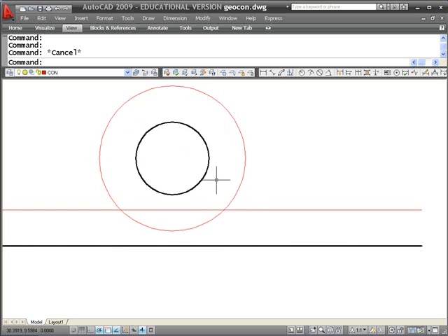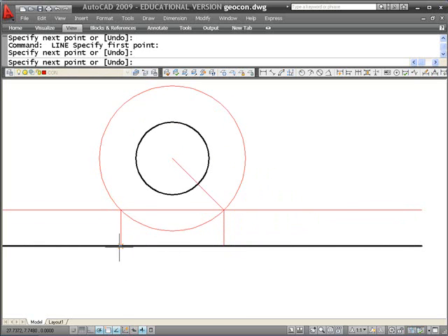And the distance from here to here is exactly 1 inch because I offset it that far. The distance from here to here is exactly 1 inch as well. If I were to draw a line from that intersection to the center of that circle, and from that intersection perpendicular to that line, do the same thing on this side, what I've done is identified my tangent points. So I'm going to have now an arc that goes along, starts right there, makes a transition from that tangency and goes all the way up and stops right here.